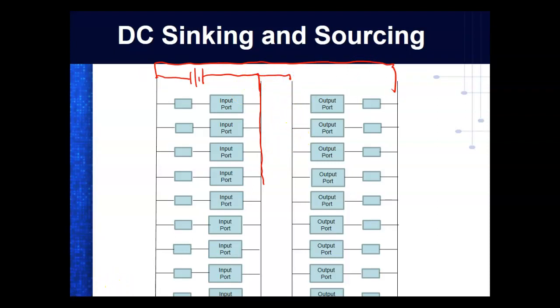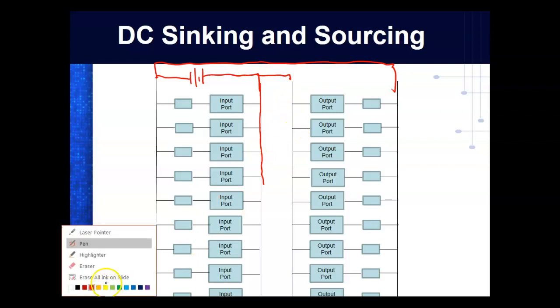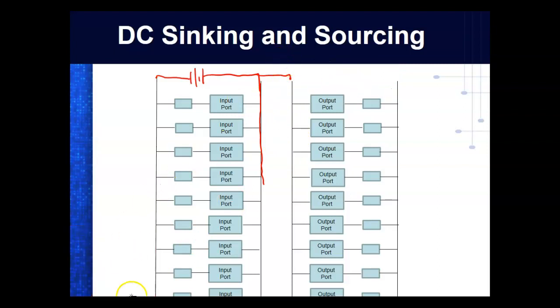Sorry. So we're running sourcing outputs. So that's right. This would run right there, and then I'd run this over to here. But still, it's one battery source. It's just the way the book is laid out. We have to draw it as two, and it doesn't show us this common right here that's actually on the PLC itself, right? That makes sense.